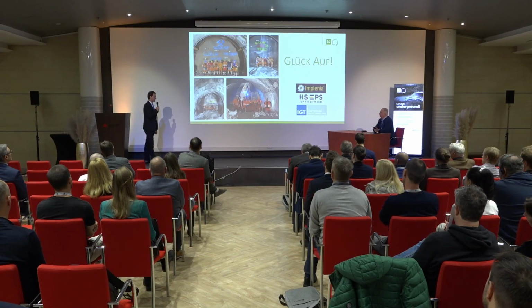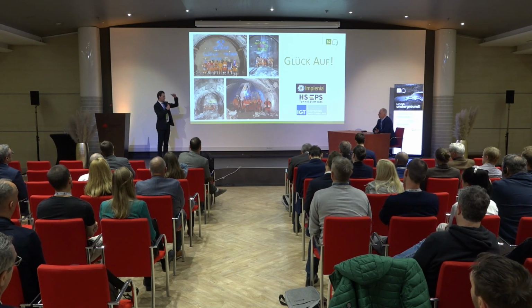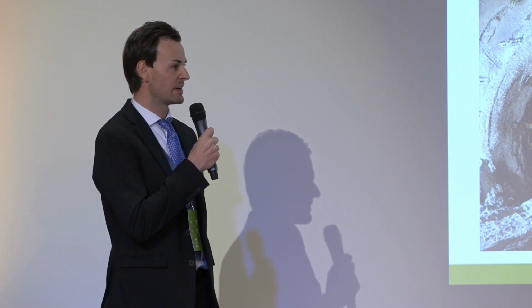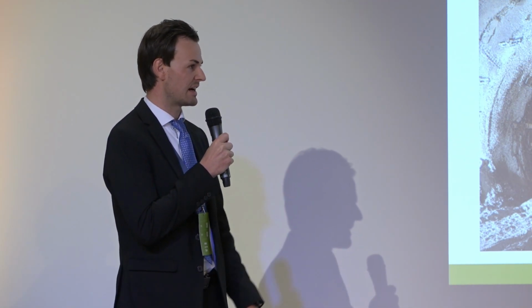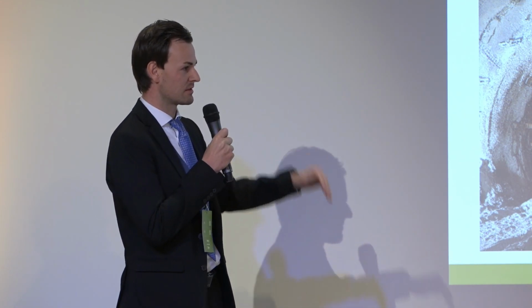I think if you have anisotropic displacements, one important thing is to reduce the height of the yielding elements. They should not be too high, because otherwise they are more prone, if the slenderness ratio is really high, to start to tilt initially. From our experience, it is good to have the full surface load transfer, which means you need a yielding element with a good geometrical shape. Reducing the height and the slenderness ratio really helps a lot. And of course, you should also apply rock bolts close above and below the yielding elements.